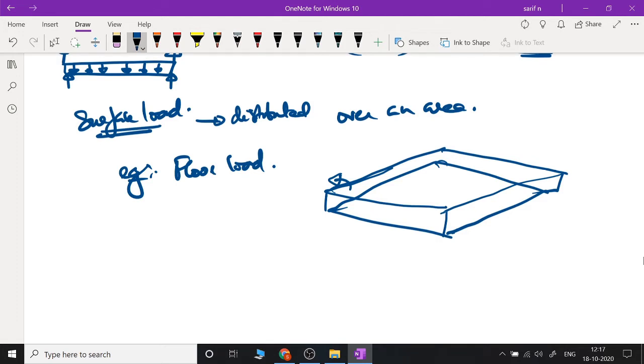Similarly, on top of the floor slab you will be having floor finish. Floor finish also will be uniformly distributed over this whole area. Therefore, the weight that is going to come over the floor slab will be uniform, or will have the same value. So what we will be doing is, instead of the earlier wall load case, where the wall was distributed along a length,